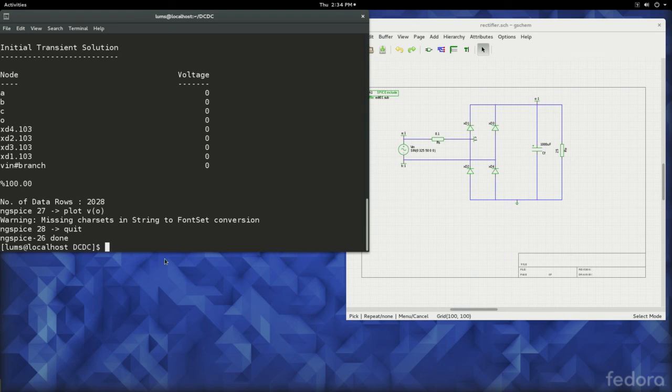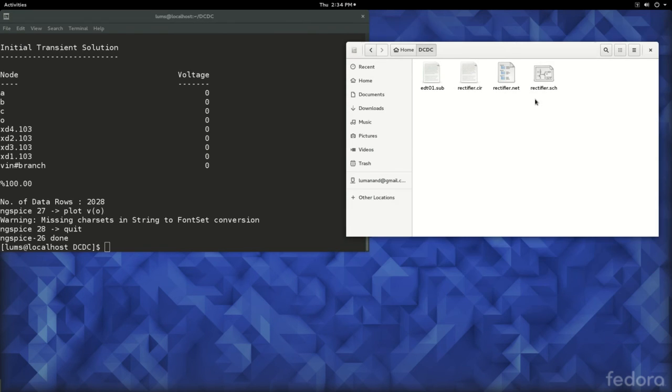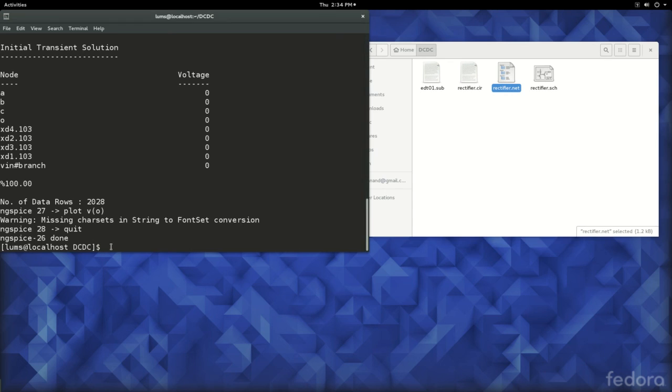And the other issue that we saw is at the time when we were generating this netlist. When we generated the netlist from the schematic, we used a command like this: gnetlist -g spice-sdb, and so on. But every time you make a change in the schematic, you have to type this out and then generate the .net file.